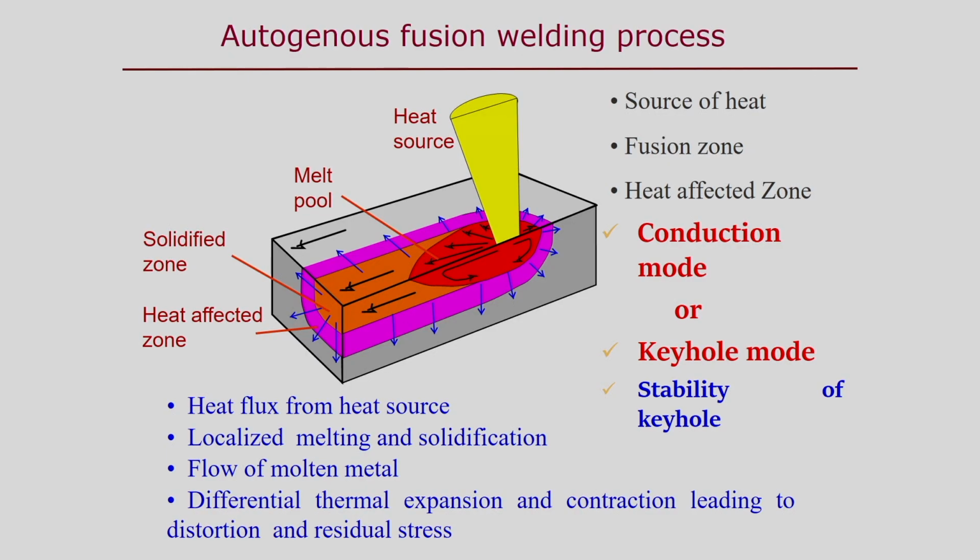So, first, the source of heat can be different, and in that sense it can be represented in different ways. For example, if there is an arc welding process, we can represent the heat source in a particular way; we will explain this later on. And if it is a laser or electron beam welding process, where there is formation of a keyhole, then we can represent the heat source in a different way. So in terms of different technology, although they are the same category of fusion welding process, the representation of heat source can be different.